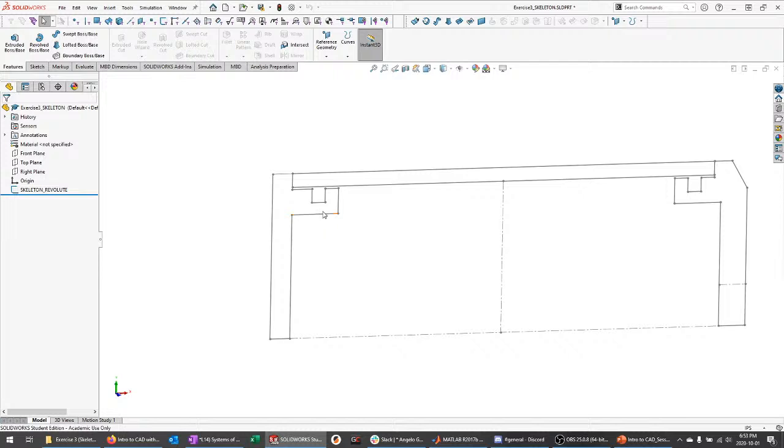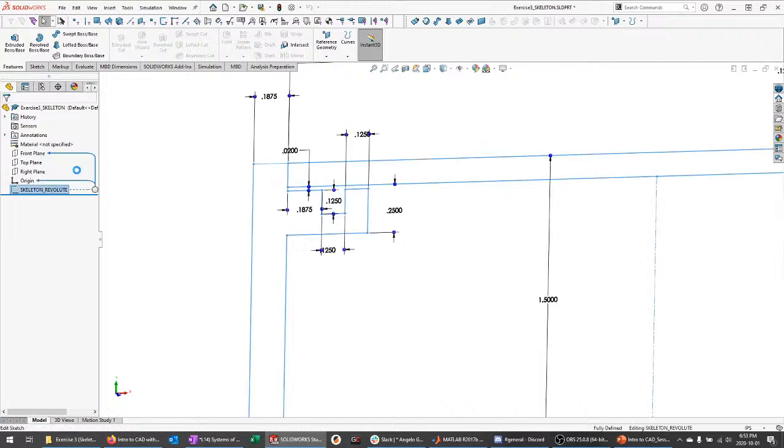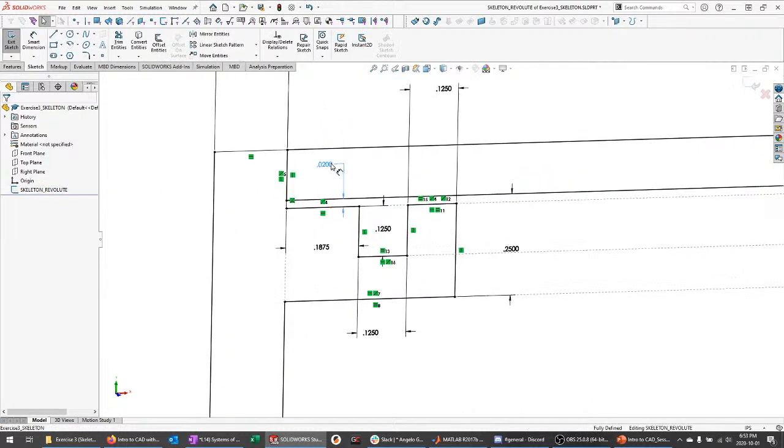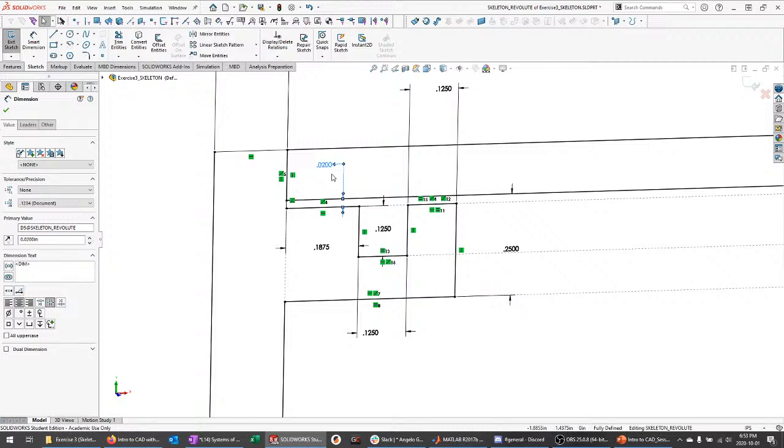At the very least, the end cap and the tube need to be interrelated, and the tube and this end cap have to be interrelated, because the effectiveness of your part is going to be very sensitive to your manufacturing tolerances and to the clearances in your nominal geometry.